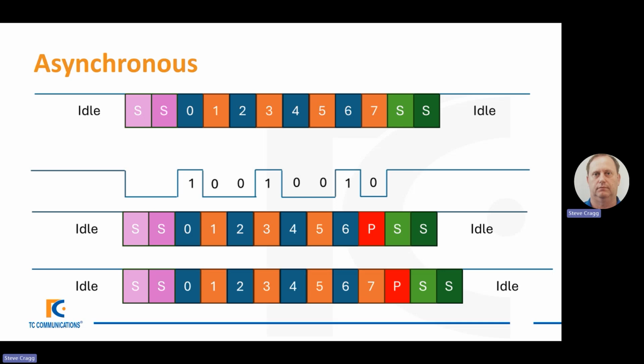Sometimes the parity bit is put in for error detection, in that if there is a string of data, and you can see the data we're sending here, 8 bits, 3 of them are 1s, that's an odd number of data bits. So you would say there's 3 data bits that are ones.